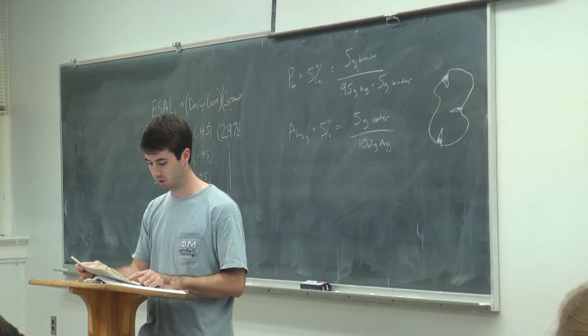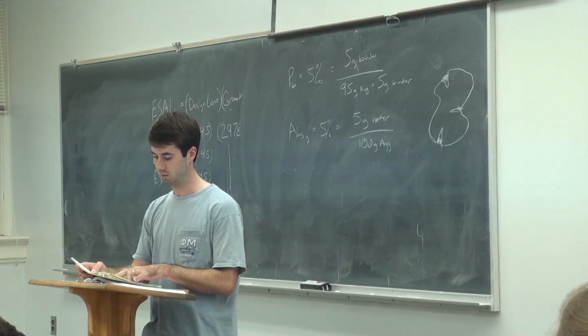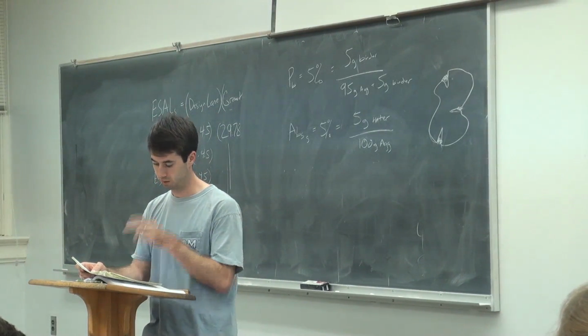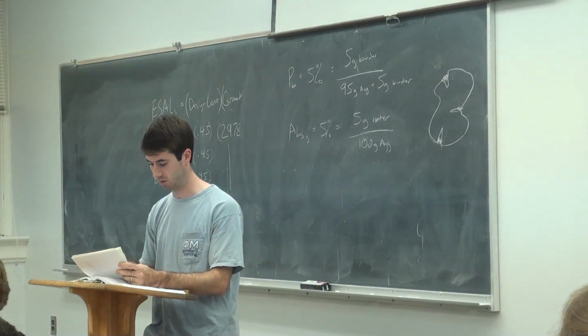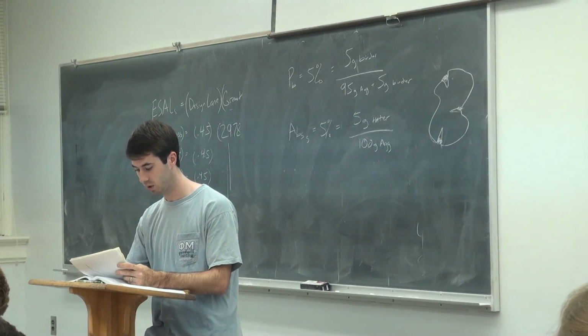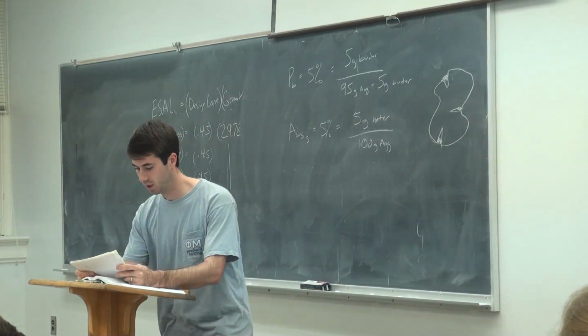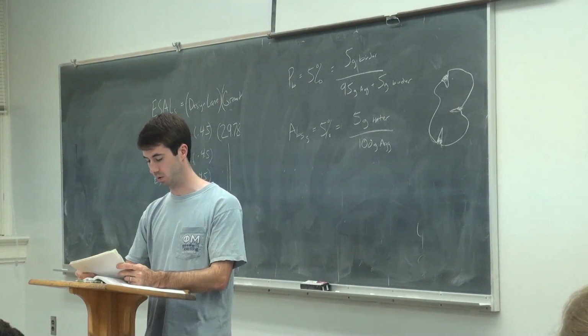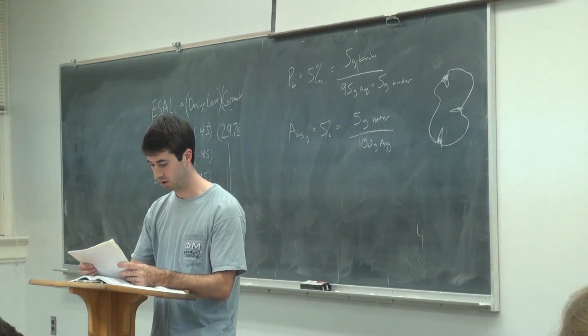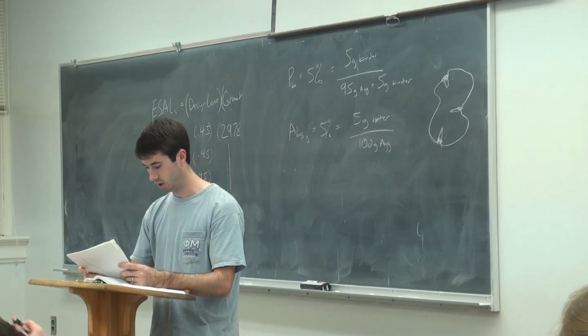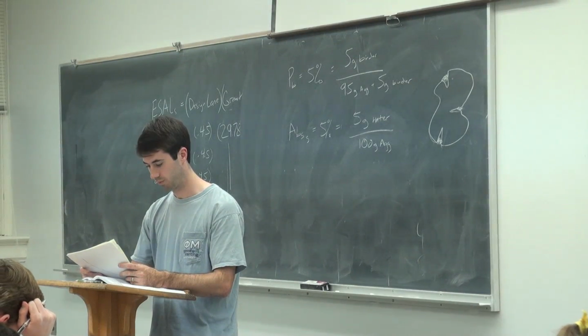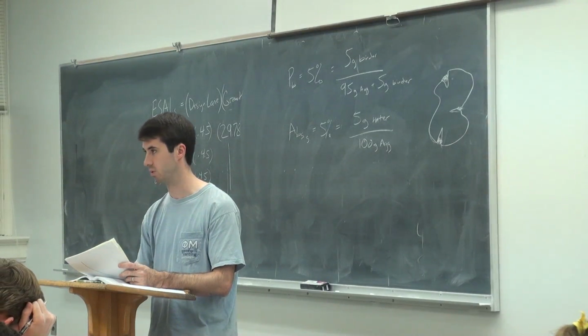And you run DSR again at what they call an intermediate temperature. They pick that based on the consistency of the binder when it comes in the door. But say we'll do 64, because that's what we have in Mississippi. So say we pass 64 on the upper end, we run DSR on the lower end, the intermediate, and we have to keep bumping up until we pass.